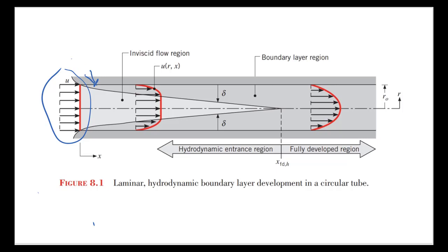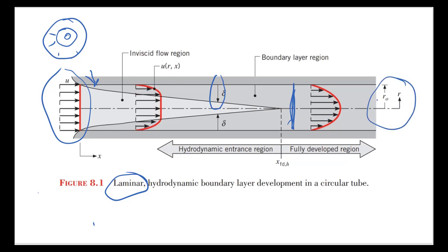All right. So the shapes that are being shown here, again, this is right out of the textbook. So they're showing the growth of the laminar boundary layer. So just like in external flow, the boundary layer will have a thickness, and the size increases uniformly if we assume we have a circular pipe. So the boundary layer is going to start increasing and moving inwards until finally it coalesces so that there is viscous effects controlling the flow through the entire flow field from R equaling 0 to R naught, or sometimes they'll call this capital R as well, depending on what book you're using.